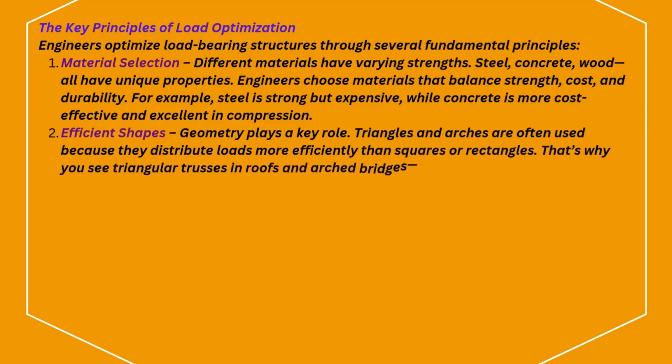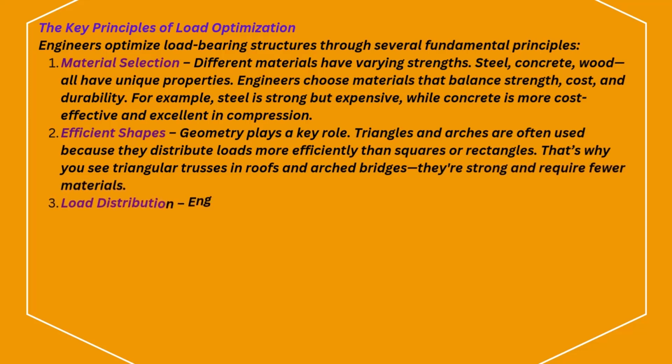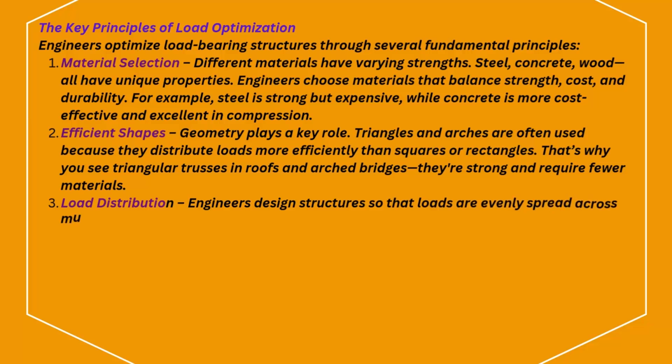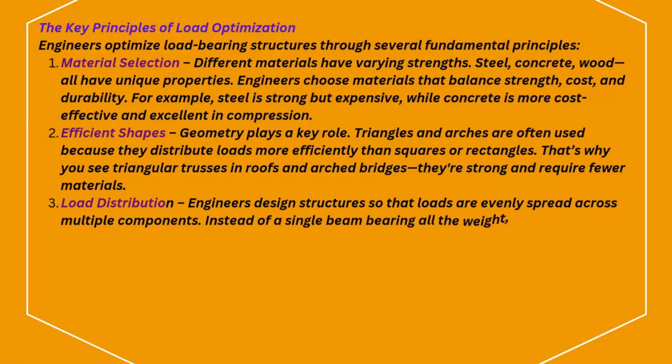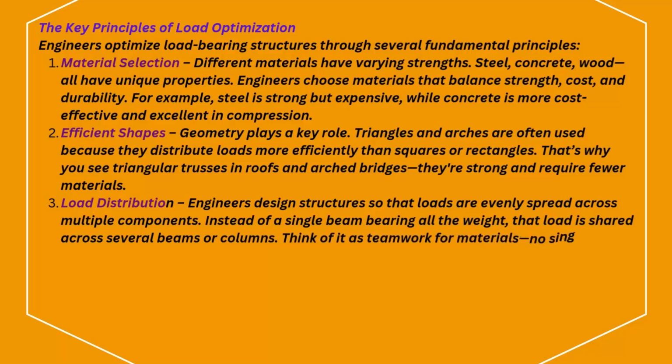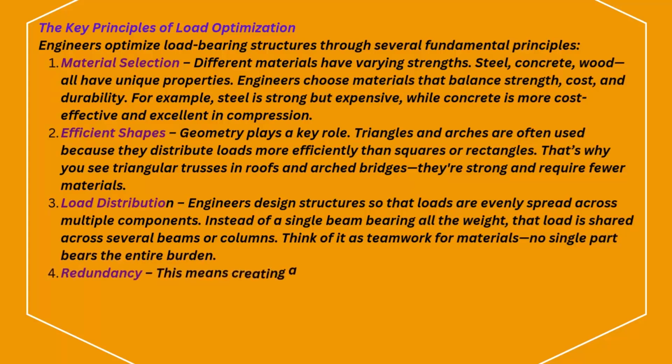That's why you see triangular trusses in roofs and arched bridges. They're strong and require fewer materials. 3. Load distribution. Engineers design structures so that loads are evenly spread across multiple components. Instead of a single beam bearing all the weight, that load is shared across several beams or columns. Think of it as teamwork for materials. No single part bears the entire burden.